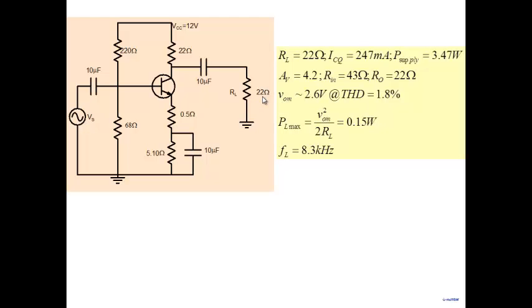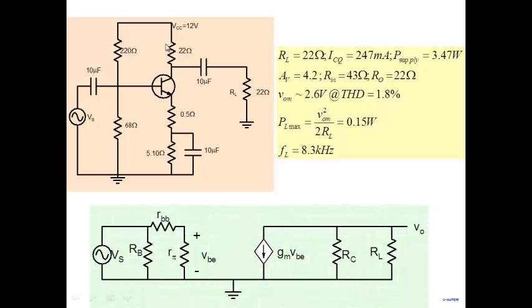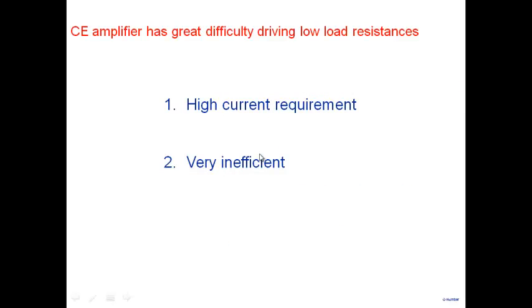What is the solution? So what I'm saying is, why are you getting into this problem? If you want to drive a very low impedance load, you need to have very low output impedance also. So in that sense, very low output impedance here. I'll come back to that. So these are the two things that are occurring.